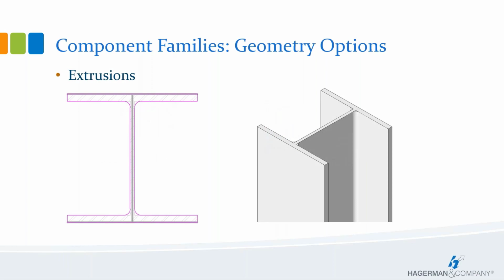let's take a look at an example of what a typical column might look like when you are modeling its underlying geometry with the extrusion command. Basically, you can use the standard pink sketch line tools to draw the geometry. And when you're done, you can see how the software literally extrudes the sketch based upon where you define the start and end planes. And I also included an image on the right side of what the final product might look like.